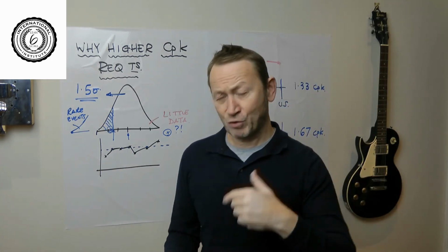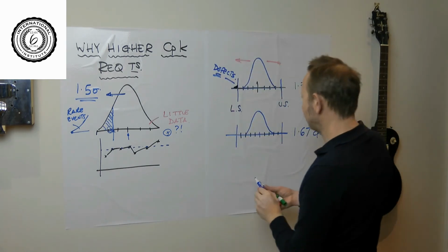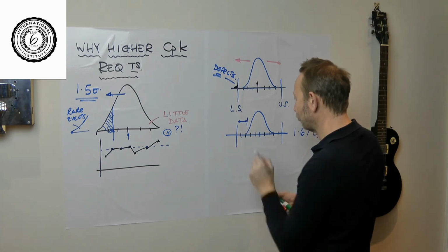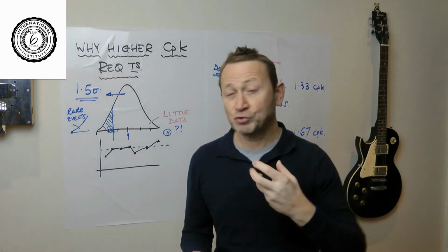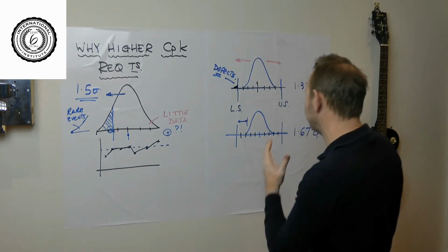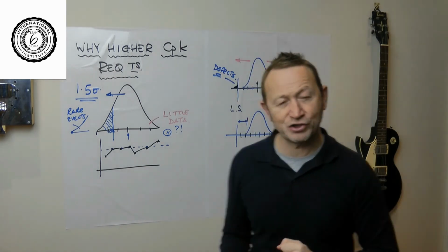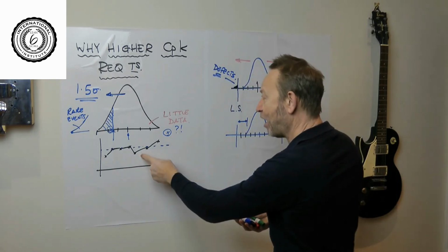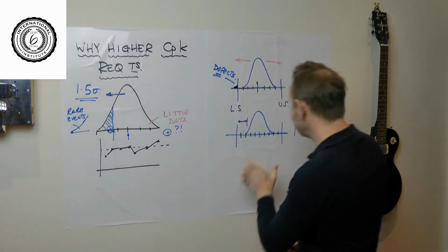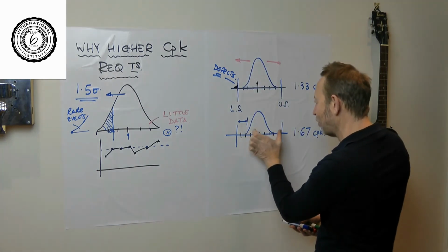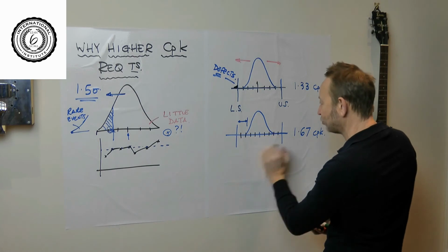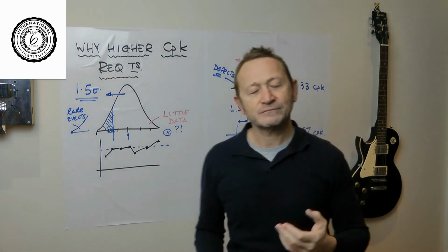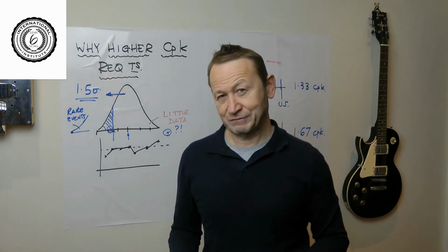So the sigma is smaller. There's more room here. So of course we have room. What do we always want room for? This is room for the variability that of course you can't control. You can't control everything. It's very difficult actually for a technician to center a process accurately because he's using a graph to do it rather than a picture to do it. So the likelihood is your technician isn't quite going to have this centered. So we want some room. Now instead of having a 1 sigma room, we've got 2 sigmas of room.